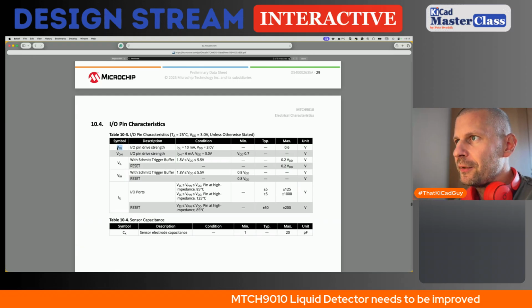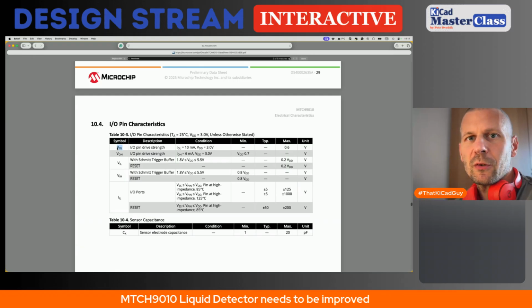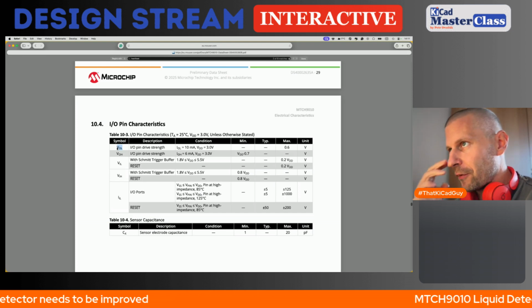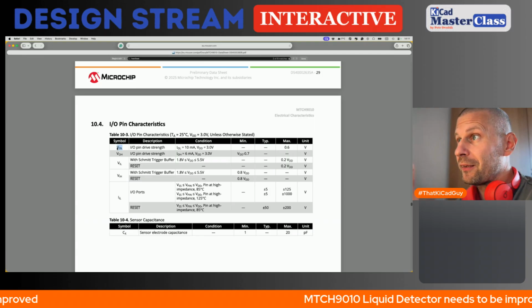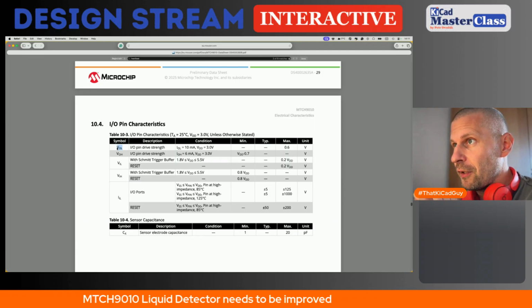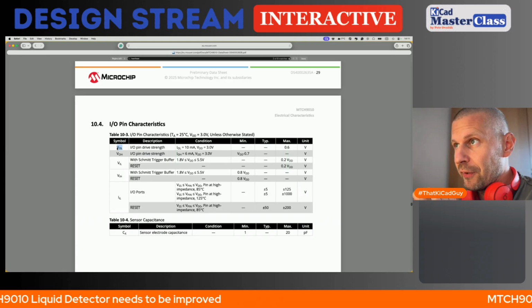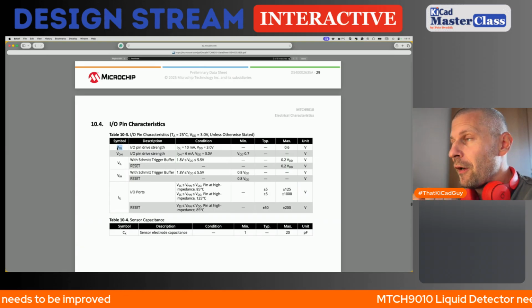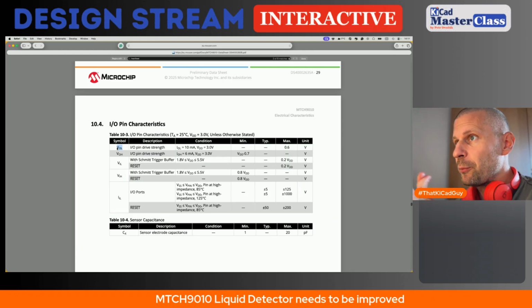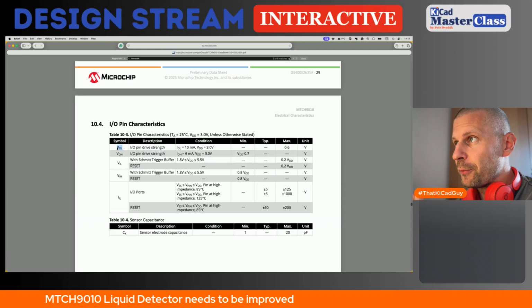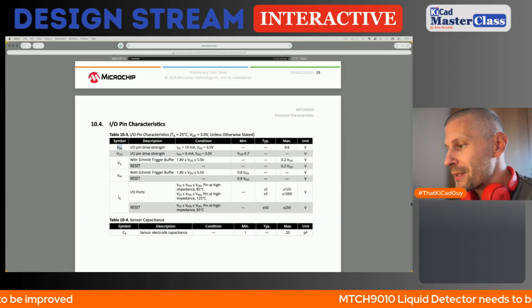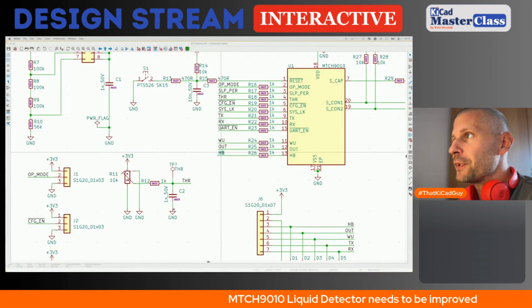The typical LED that I'm using in 0805 package size, when driven with the current of 1 milliamp, it lights like crazy. So this will be definitely enough, and the output pin will not be overloaded with this current. So heartbeat and output will be monitored by the LED, connected or sourced directly from this port.